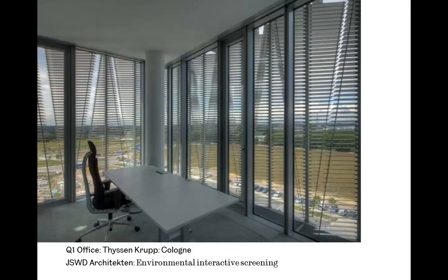We tend to talk about shading as a kind of discrete shading device on a window. Screening is more this, where the entire window is covered with a screen. This is much more effective at controlling solar shading. It's also much more expensive, and any of these systems which have movable items, there is a maintenance cost. You have to make sure they keep working.